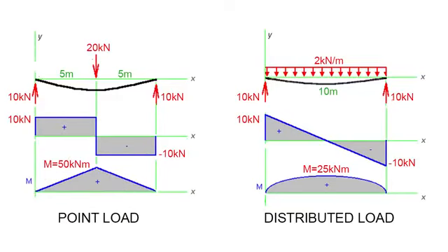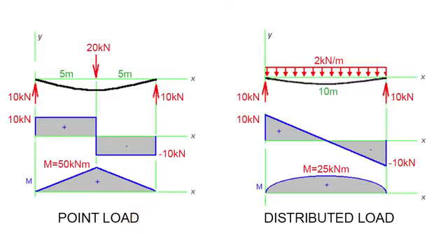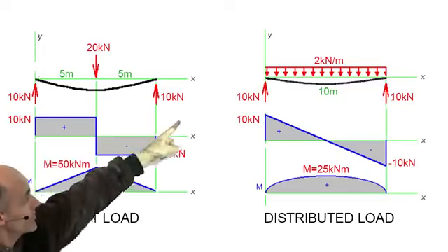Positive, negative. Bending moment diagram, 0. So that's 5 times 10 gives me 50, and this is negative 50 back to 0. Right, so my maximum bending moment is 50 kilonewton metres. Is that positive or negative? Being pushed from the top, that's positive. It came up positive in my graph anyway, so that's positive. Positive bending moment, sagging. All right, now let me draw this one.